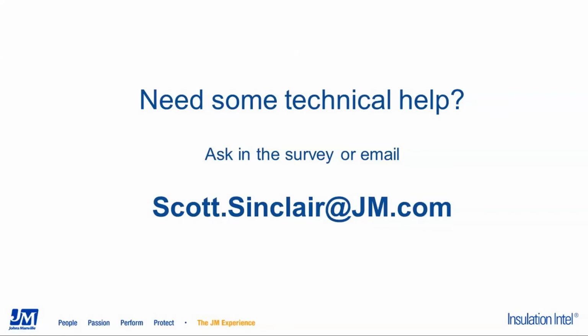Okay, thank you. And then a little bit more on the testing. Why was the temperature of 400 Fahrenheit selected for cyclic testing when most corrosion occurs between 150 and 210? Mostly just to ensure that we fully dried out the material during the dryout time. We wanted to ensure that we didn't have any residual moisture in the material. That way we could ensure that we were getting full submersion and any sort of possible extraction of the inhibitor from the insulation itself.